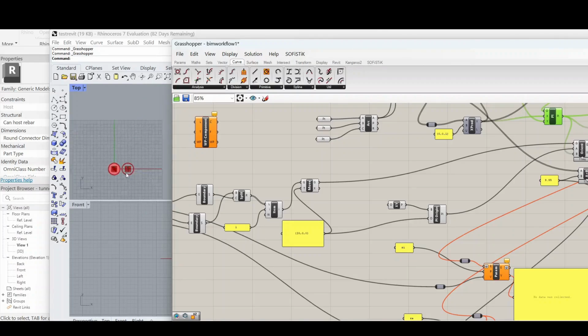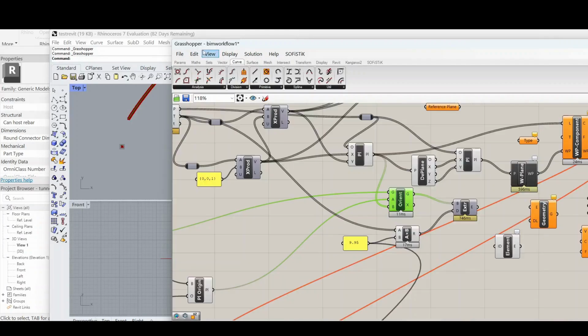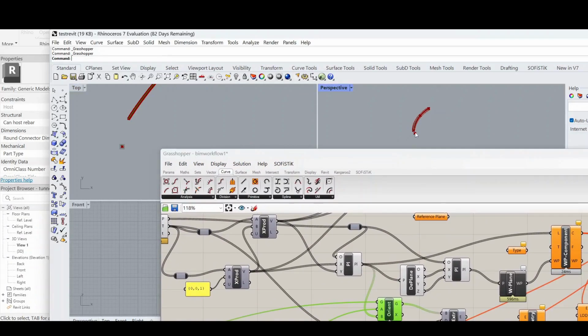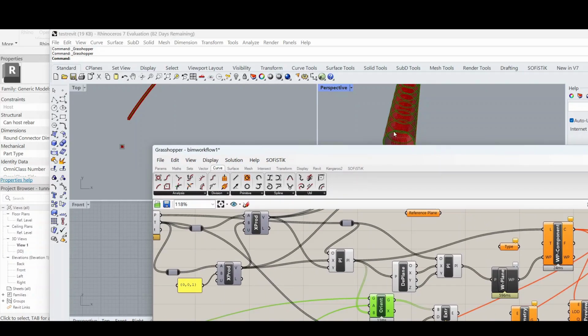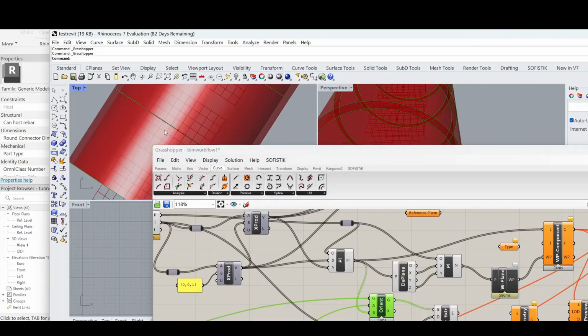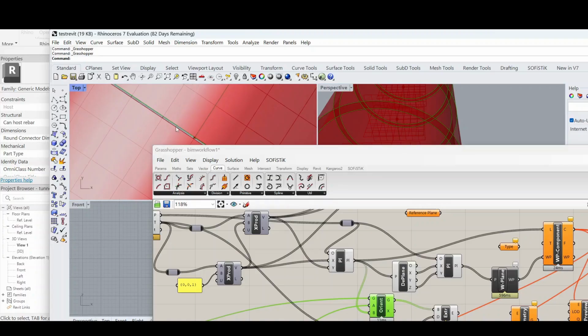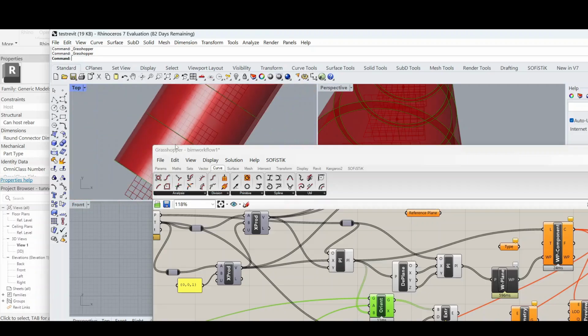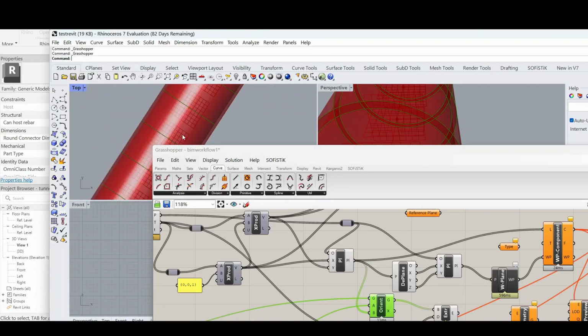After orienting the tunnel cross-section onto each perpendicular plane, I moved the sections into position and extruded them. The extrusion length is 9.95 meters. I intentionally left a 5-centimeter gap between blocks. This gives us a fully parametric tunnel composed of multiple blocks.